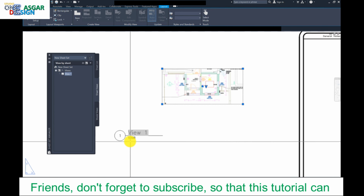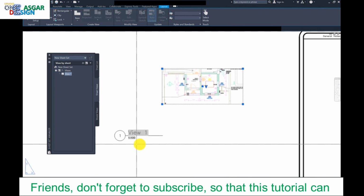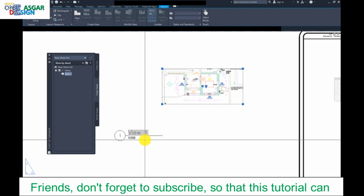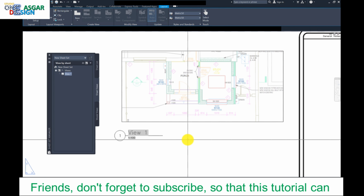In the past video, we manually created this, meaning that if we were to ever change the scale, we'd also have to ensure that we change the text. Using this dynamic title erases all possibilities of human error. So I'll revert that back to 50, type in RE for regen, and it will regen.